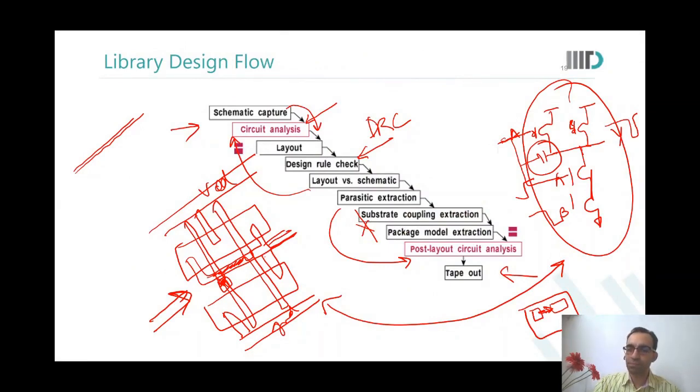So it's like source to body capacitance and so on. We take that into account. Yes, because source to body junction capacitance will always exist. Junctions would toggle, so there would be some current in the source, and that can lead to noise for other circuits which could be sensitive to that noise. In this course, since we are looking at digital circuits only, such noise is not really bothersome for us.